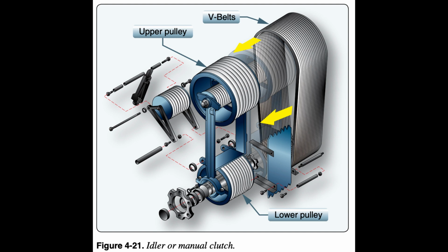Some aircraft utilize a clutch for starting. This allows the engine to be started without requiring power to turn the transmission. One advantage this concept has is that without a load on the engine, starting may be accomplished with minimal throttle application. However, caution should also be used during starting, since rapid or large throttle inputs may cause overspeeds.